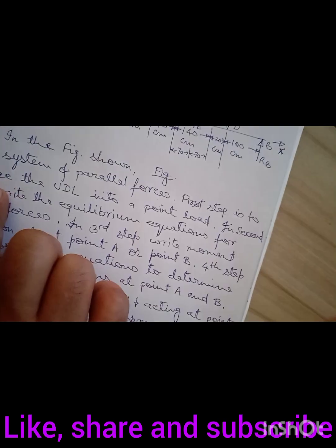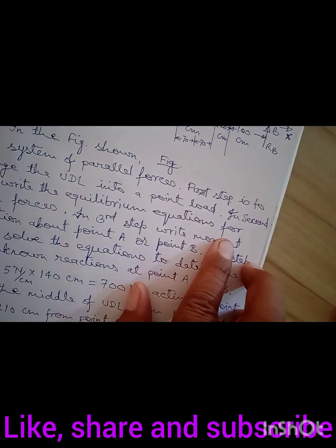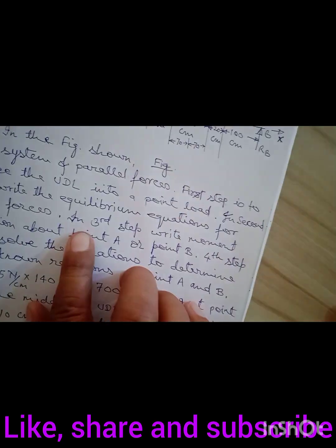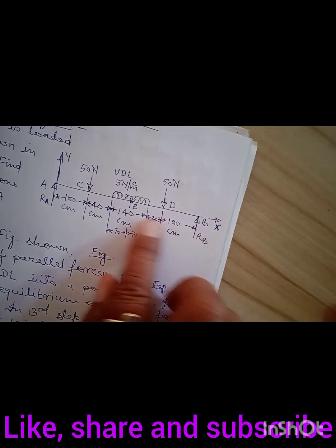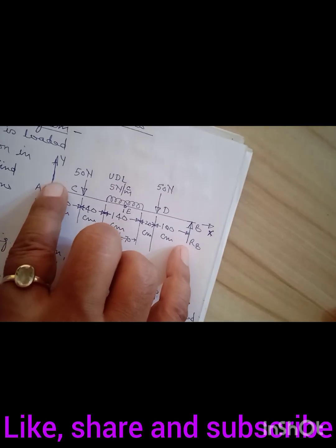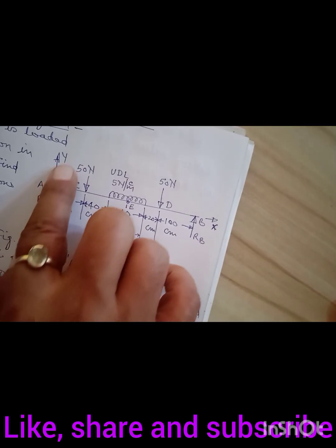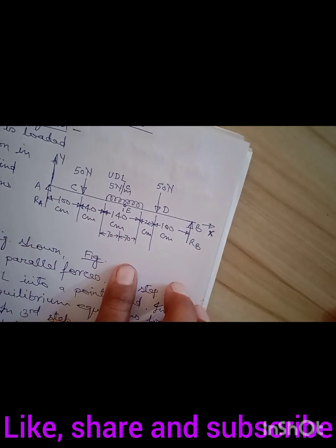In the second step, write the equilibrium equations for the given forces in x direction and y direction. Here x direction is taken along the beam as shown in the diagram, and y direction is perpendicular, normal to the beam, as shown at point A.